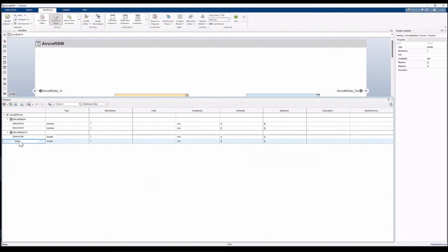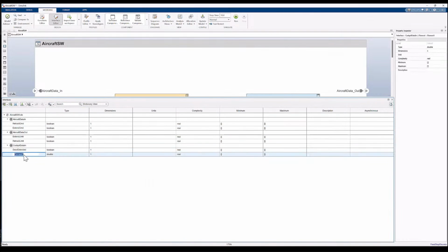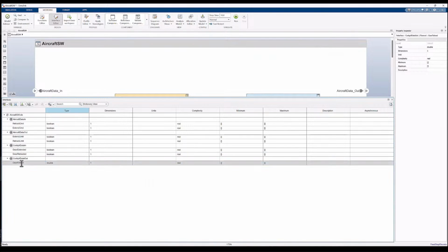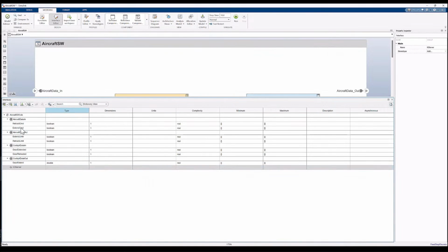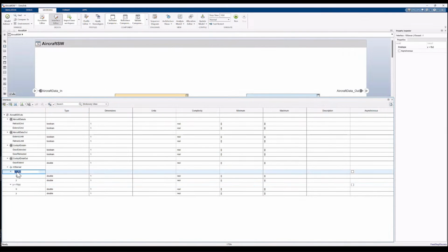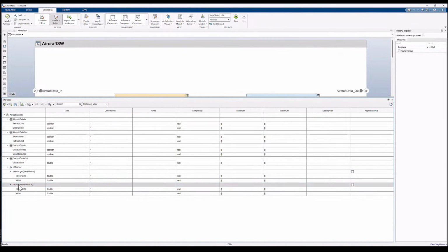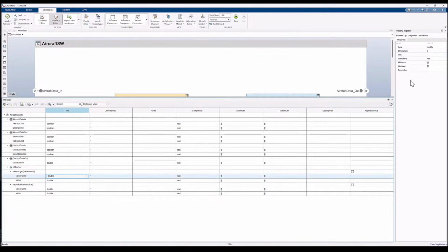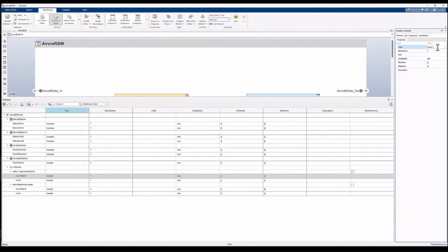Real quickly, we're going to rush through this to establish all of our base interfaces. And then I'm going to create a service interface. And like I was talking about before, this is different in that now we're going to specify function prototypes, and System Composer parses those prototypes and lets you set the data types of your input and output arguments. So in this case, we'll set this in the property inspector to be an enumeration type, and that's going to be our hardware channel mapping.